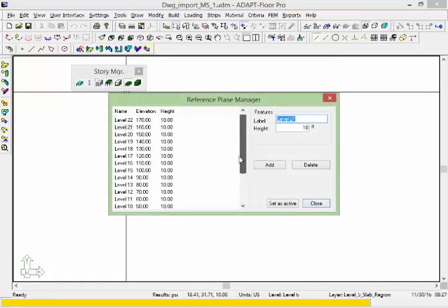What we do need to do, however, is insert another level. Level 5 really is not the bottom level. Level 5 is the first elevated level. So we want to insert a level below level 5. However, the program currently does not allow levels to be assigned below the lowest level or the level that is selected. So if I select add, you can see that the program adds a level between 5 and 6, and it's actually called plane 19, which was the next level in sequence through automated level assignment or through addition of a level here.